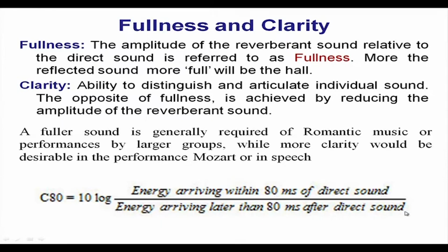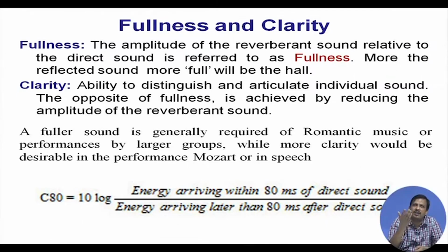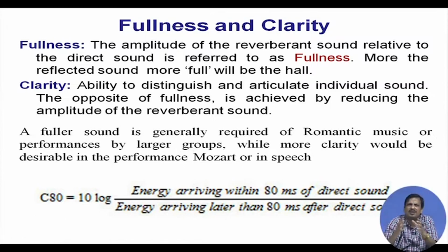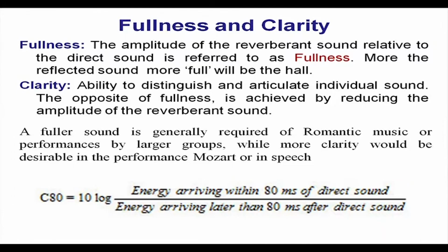80 millisecond after the direct sound. So, within 80 millisecond of the direct sound, some energy will come, and that energy is defined by the clarity. A fuller sound is generally required for romantic music or a performance by a larger group. So, I require an ensemble, or you can say a full sound, I do not want to identify who is performing, because a huge large group is performing. So, individual artists I do not want to identify. What I want is a full sound, sound intensity should be very high.